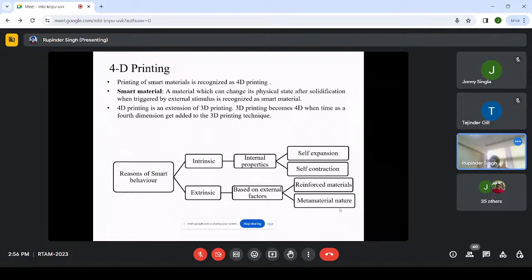In a truss, what is important? The length of the link and the angle of the link. So the total Young's modulus that is coming for that material is not because of the inherent property of the material, but is dependent upon the length and the angle of the link, which may be capable of giving the same property or a better property than the solid structure. Based upon this, we can even have hollow sections or much lighter sections as compared to the solid sections, specifically in the case of the railway bridge.